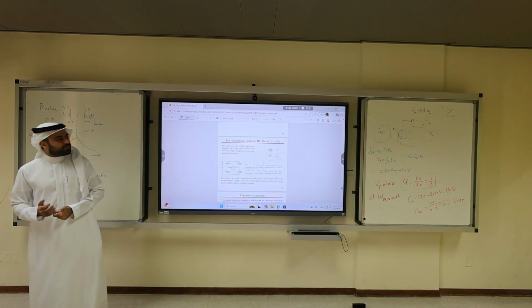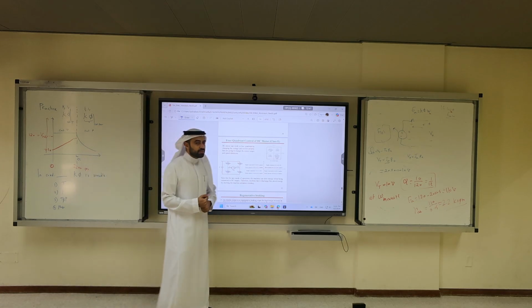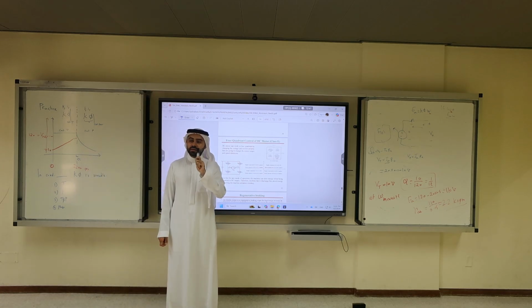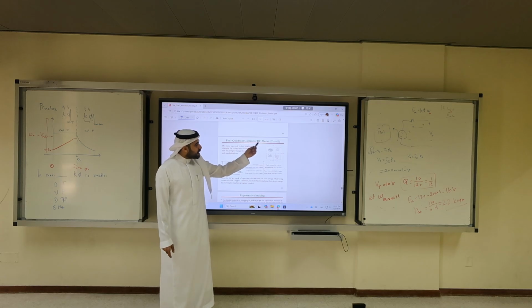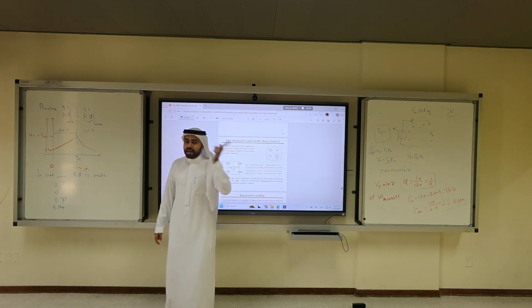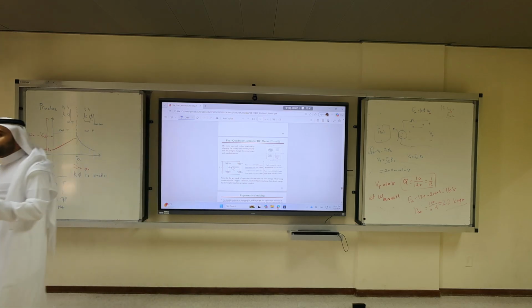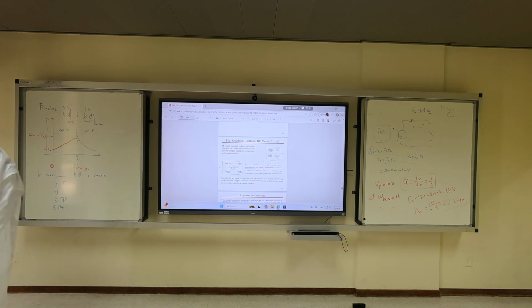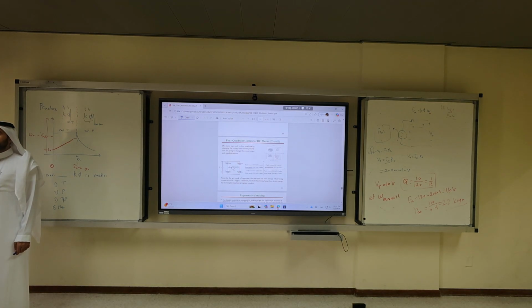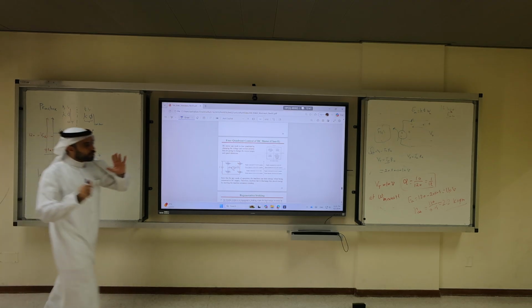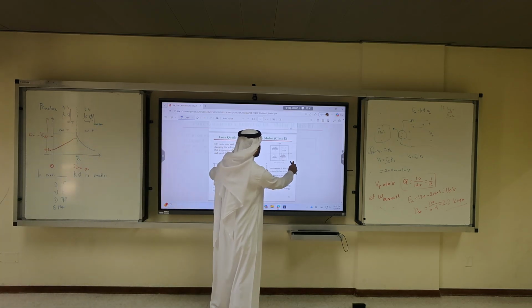Let's talk about the 4-quadrant control of a DC motor, what we call Class E. Are we familiar with Class E? What classes did we have for induction? Do you remember? A, B, C, D. We did not have E. So Class E is reserved for DC motors that work in the 4 quadrants of operation. Keep in mind, in induction machines we don't have 4 quadrants of operation. We had 3 modes of operation, but for DC machines, we have 4 modes of operation.